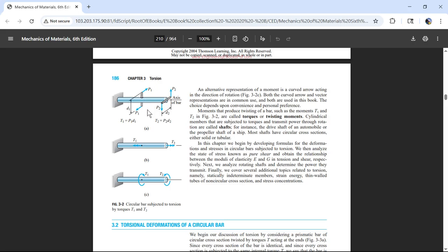I mean, it is a huge fundamental, and hopefully I'm not glancing over something, but because you have some of the forces in the cardinal directions, and you have some of the moments. In statics, those are going to all equal 0. If they're not equal to 0, you're going to have motion. In the cardinal directions, you're going to have motion in that x, y, z direction. If you have the sum of the moments not equal to 0, you're going to have some sort of rotation. But still, even rotation is just mass moving.